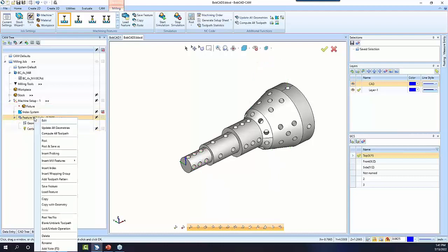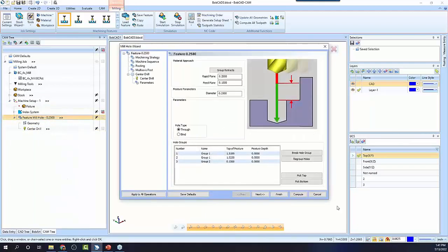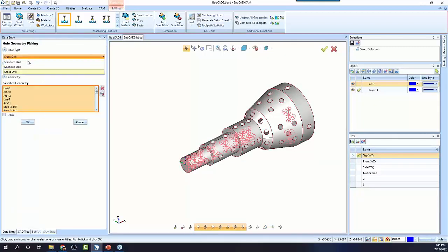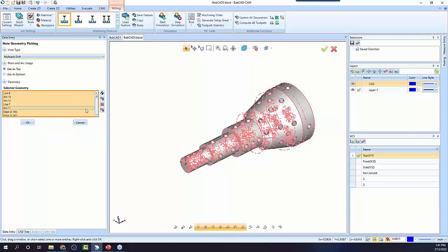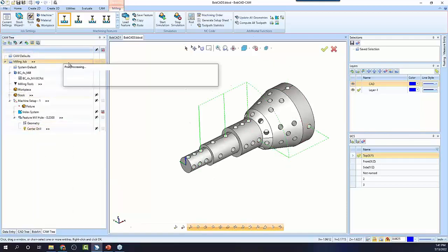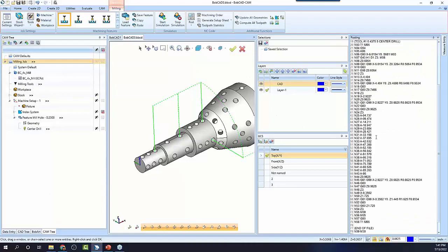Now, you could, in a case where you have a 5-axis software and you're running it on a 4-axis machine, you could still use multi-axis drilling to drill them in Y. But what you wouldn't do is pick the holes that required a 5-axis move. Instead, you would just pick the holes that required a 4-axis move, whether it was off-center in Y or not, right? So that is another workflow that you could use for that. And you can see I was able to post the code out